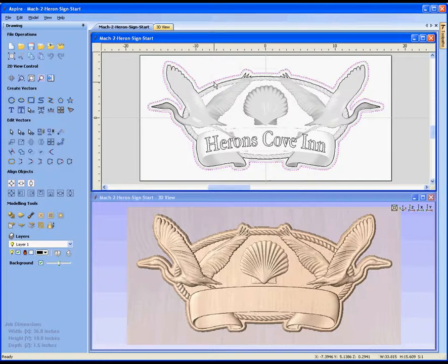What it would be nice to do though is to offset that outwards, because if you remember, when I'm cutting with a ball nose cutter on a finish cut I need to make sure that the boundary is a bit bigger than the size of the part. That way it'll allow the edge of the tool to roll over the part and not leave any kind of a lip. In this case I'm going to finish cut this with a 1/4 inch ball nose cutter, so I can offset this out anywhere up to the radius of that tool to get it to roll over without rolling all the way down to the back plane.